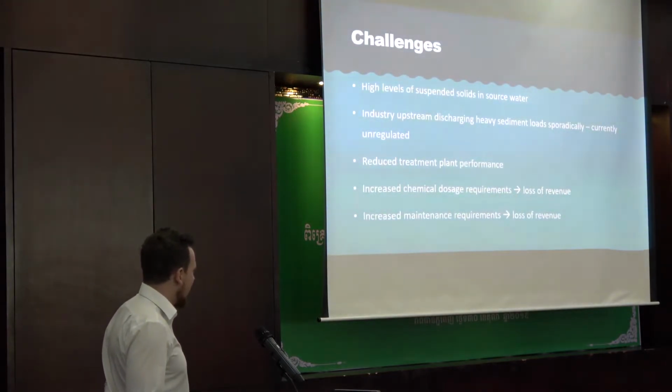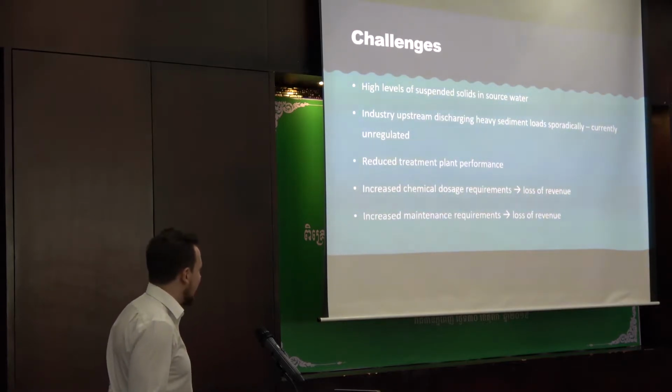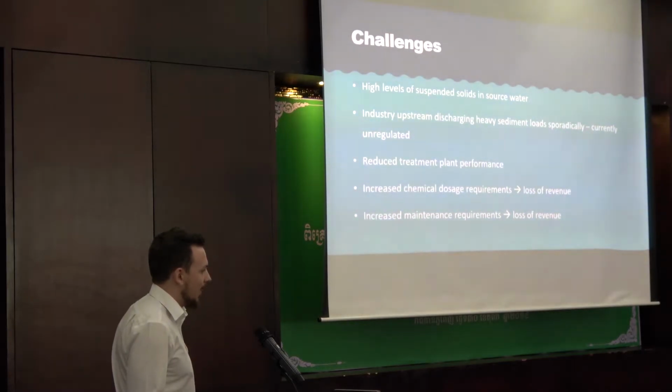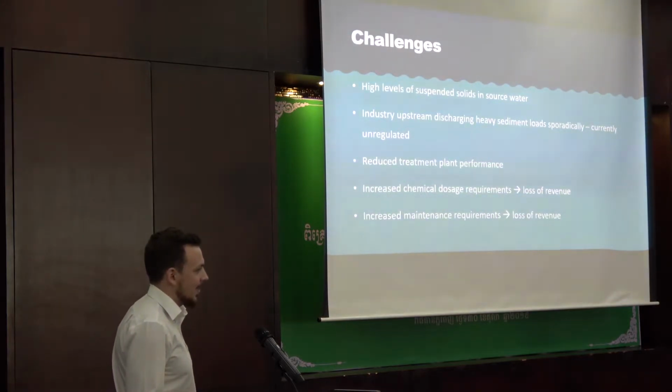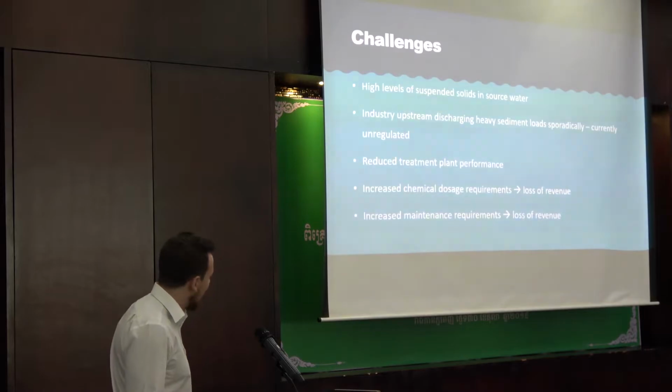So there's high levels of solids in the water. It's having an effect on their treatment plant by severely minimising its performance. We're seeing severe loss of revenue as a result of increased dosage requirements, both PAC and chlorine, and an increase in maintenance requirements as the high sediment load damages equipment and continually causes block-ups.